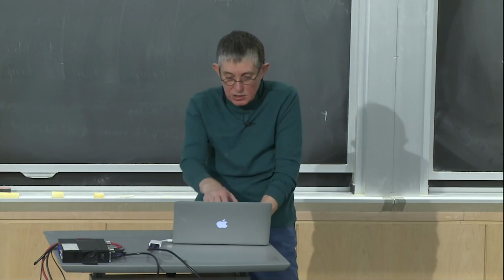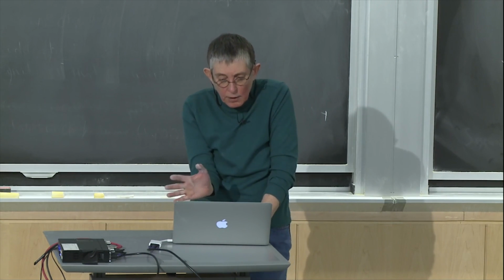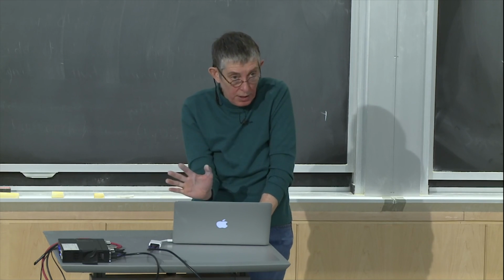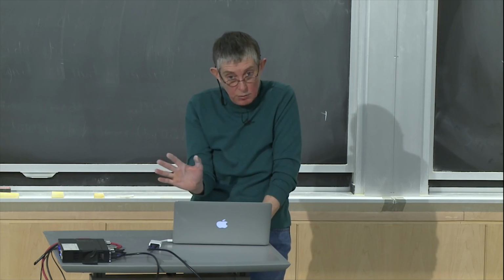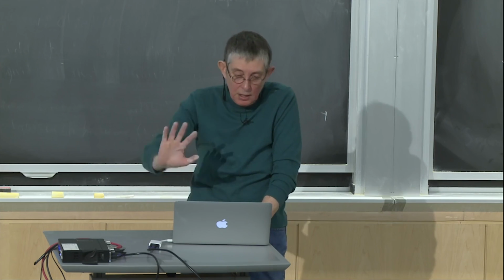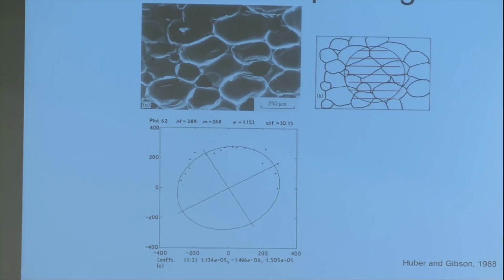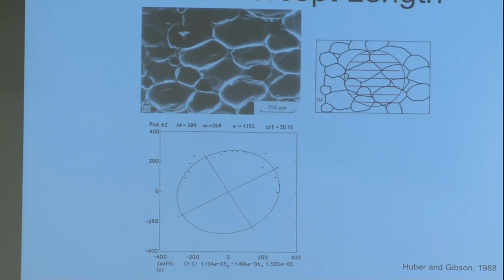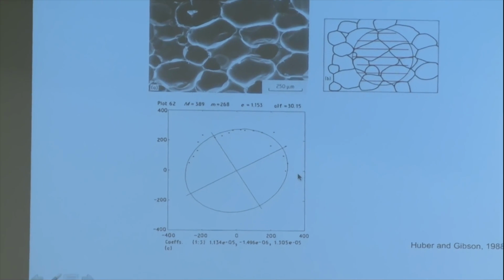And then, because this is just in one orientation, you would rotate those parallel lines by, say, 5 degrees and do it all over again and get another length at 5 degrees and one at 10 degrees and one at 15. And so you get different lengths for the intercepts as you rotate your parallel lines around. And then you make a polar plot, and that's what the thing is down on the bottom here.